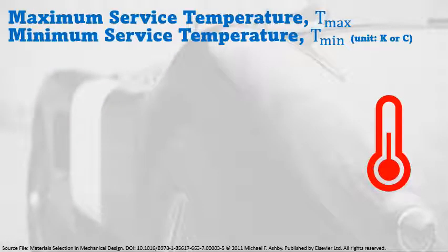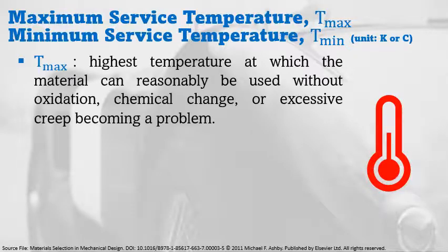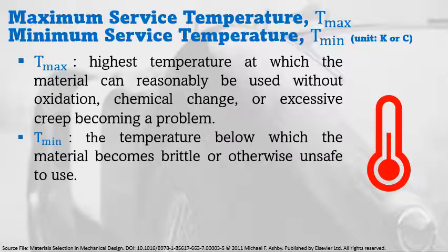On the other hand, the maximum service temperature and the minimum service temperature are defined as follows. Tmax is the highest temperature at which the material can reasonably be used without oxidation, chemical change, or excessive creep becoming a problem in the operation. The minimum service temperature, on the other hand, is the temperature below which the material becomes brittle or otherwise unsafe to use.